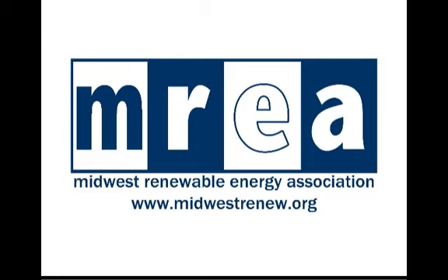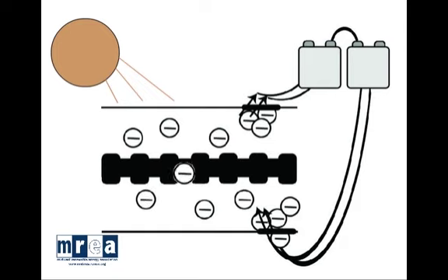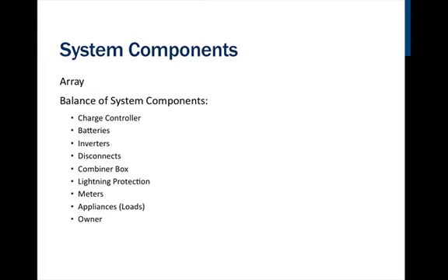In this animation, we're going to take a closer look at what happens inside the solar cell when the solar radiation strikes a panel. Here we see just one electron's path across the process. The electron is knocked loose from an atom within the solar cell. It travels through the p-n junction, which is the black bar in the middle, and is forced up to the top layer. In the top layer, it doesn't find an atom to latch onto because of the overall abundance of electrons in that layer. Instead, it travels toward the path of least resistance, which would be the conduit and battery shown as the load in this case. After powering the load, it returns to the bottom layer of the solar cell, only to go through the process all over again.